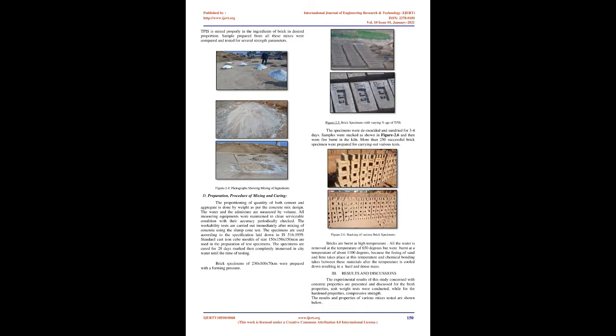The second mix, TPSC series, had toothpaste waste powder, TPIS, as a replacement of cement. The third mix, TPSS series, had toothpaste waste powder, TPIS, as a replacement of sand. The compressive strength tests were conducted to monitor the strength development of concrete containing up to 20% of this pozzolana as cement and sand replacement.